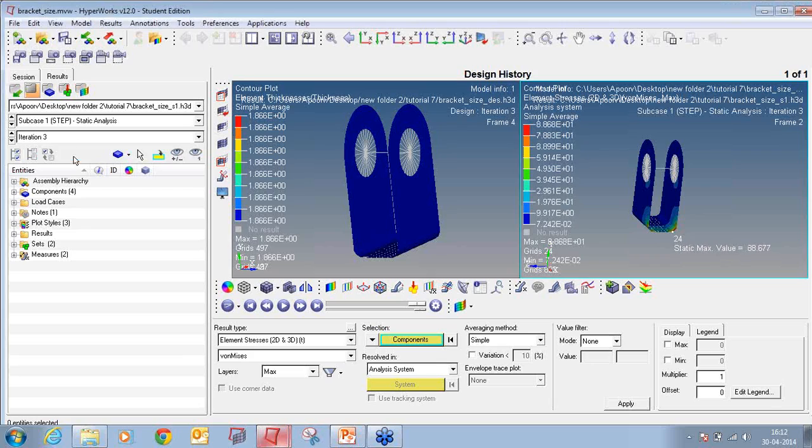So for this particular component, I am allowed to get some higher values of stresses. But I want to reduce the thickness of the component so that the cost of the component will decrease. So by reducing the thickness, it will increase the stress, but my allowable stress is 100. So I am getting the stress lower than 100, which is 88, and thickness is changed drastically to 0.7 mm approximately, which is a big thing. So in this way, you can get a variable change in the thickness, that what thickness is required for what values. So as per the constraints or the objective, you can define the size optimization.